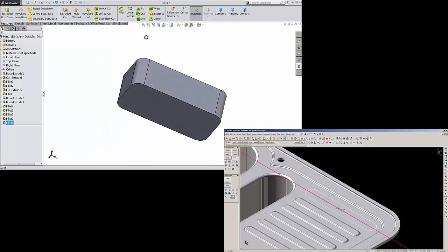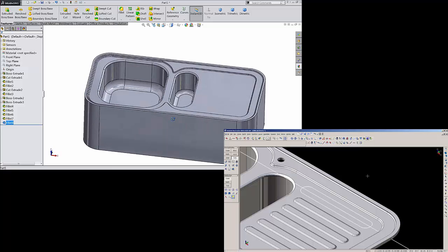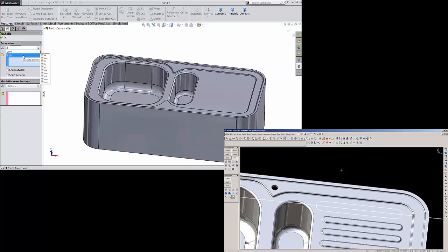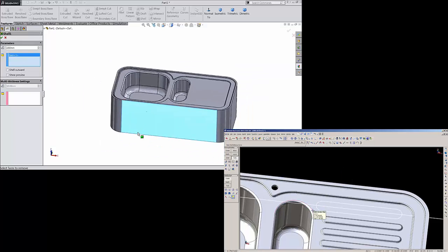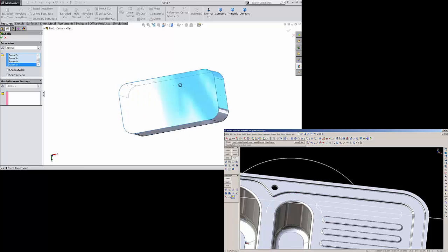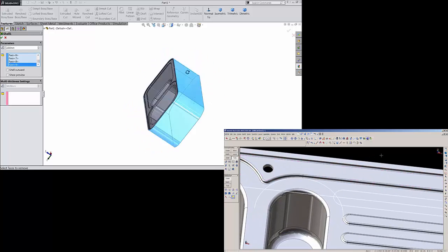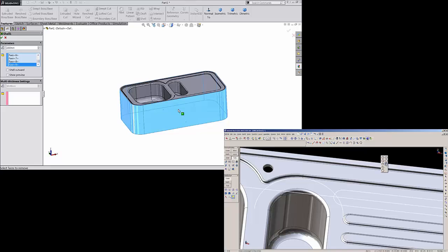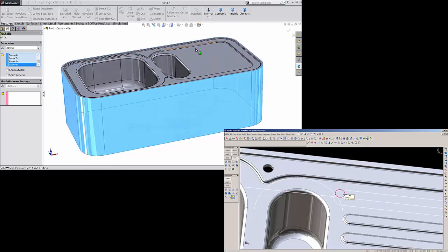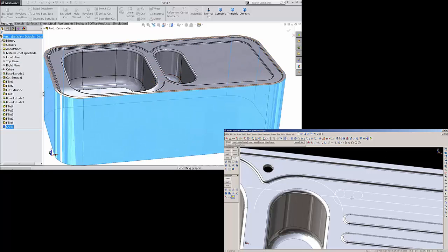Now it's time to use this shell command and give the proper shape to this wash basin. Keep shell 2.5 mm and select the faces. Which face you don't want to keep, just remove. Except front, we selected all the faces and we want to remove. Select here OK.